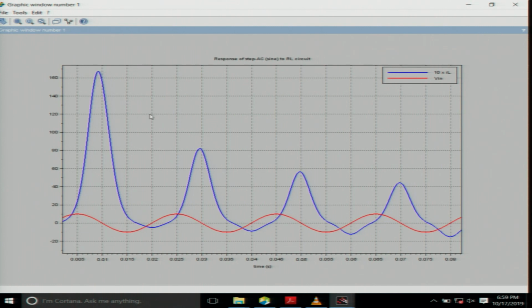And because of the nonlinearity, the current is almost scaled, this is almost 10 ampere, more than around 20 ampere the peak value. The current is scaled, it is multiplied by 10 here. It may not be very visible to you, but roughly it is around 18 ampere.